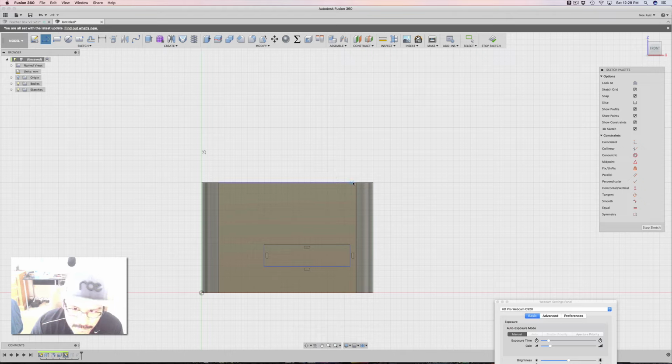So if you roll over an edge inside of Fusion when you're in the edit sketch mode, you'll see that as you go down, your cursor gets locked to this thing. You can see my cursor is moving a little bit. If I go down here in the center, where I think is the center, Fusion will let me know that it is the true center, and it's locked there. And it gives you this icon of a triangle. That triangle lets you know that you are indeed in the center of a given edge, whichever edge your cursor is currently on. So I want it to be up here. So I'm going to click on that.